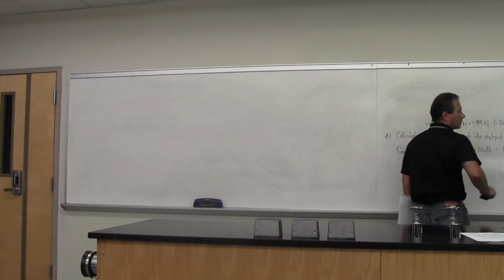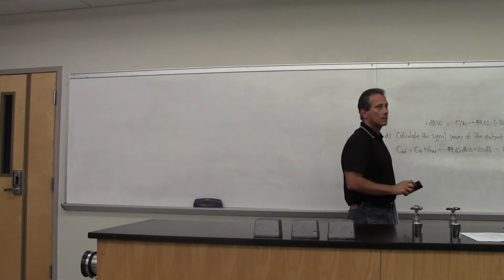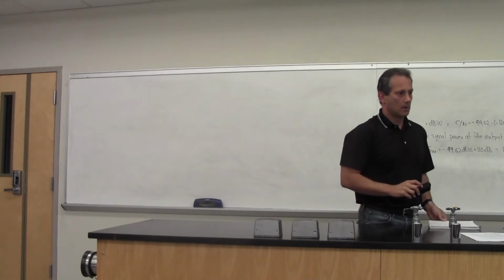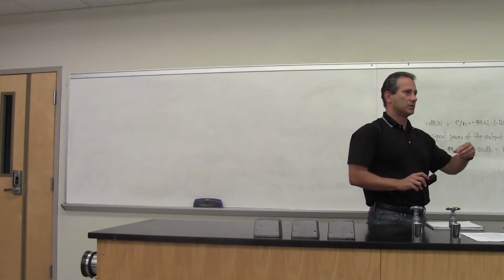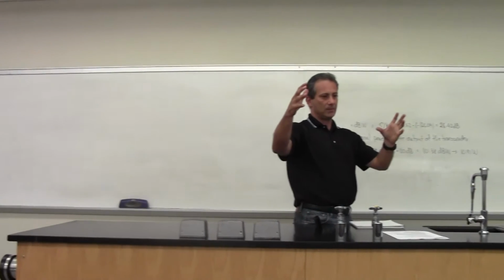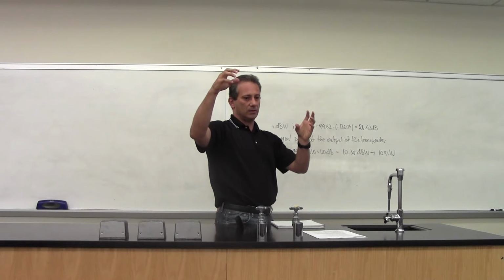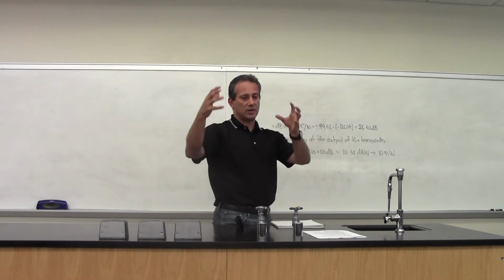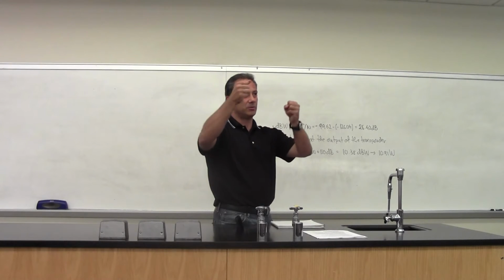What happens to the noise at the output of the transponder? It stays the same? It's going to be multiplied by the gain, the noise that is at the input of the transponder. Remember how we treat the transponder? We take the whole system and calculate the system noise temperature, which means you take all the noise out of the system and put it up front.